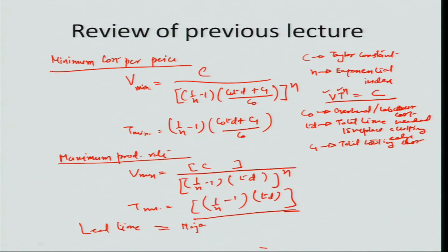Let us say the major setup time associated with the process is some value, we can call it probably Ts, plus the amount of time of processing for one component, the amount of cutting time, which we call Tu, times the lot size q. So that is how you actually calculate the average lead time in this particular case.